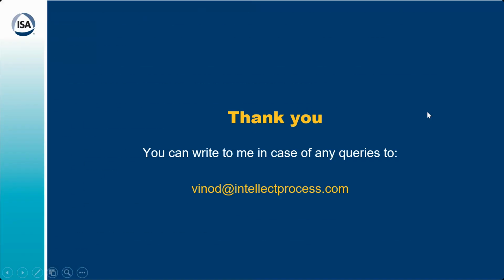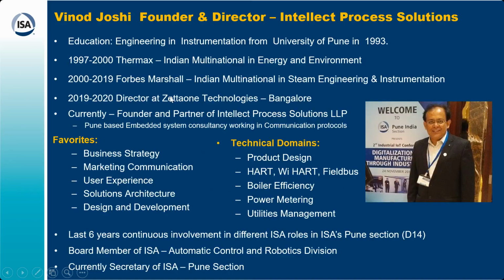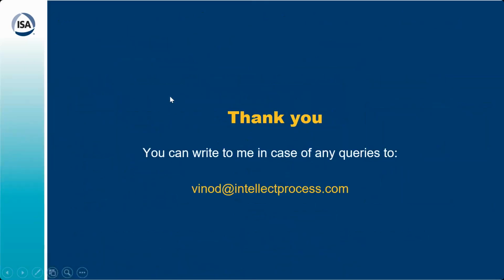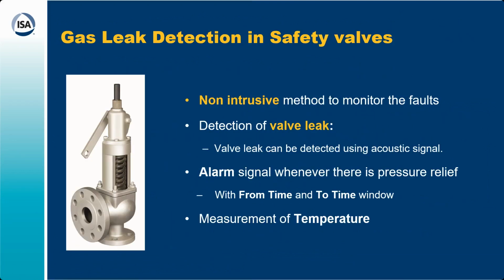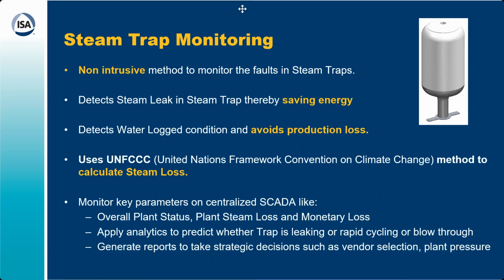While selecting a gateway, is any particular system compatibility to be checked, like the version of the software? Okay, I'll just go through that. So some compatibility with the version of the software or whatever. Yeah. So all these HART gateways normally work with both HART 5 and HART 7, HART 5, HART 6, HART 7 versions.